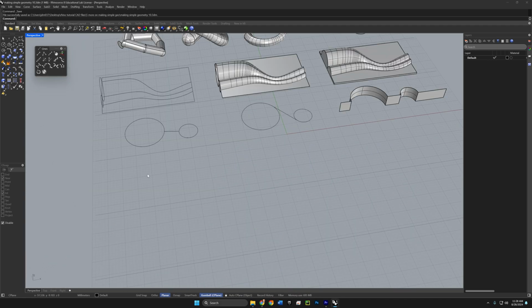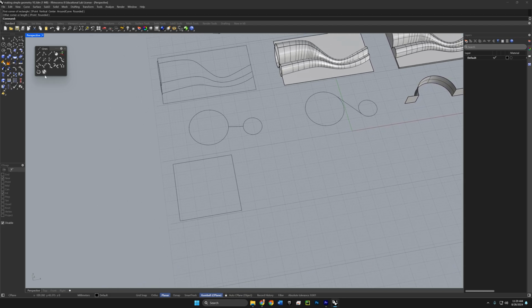In our next example, we'll look at how the curve Boolean command can help to speed up complex trims. We'll start out by making a rectangle, and we'll click here, and we'll hold shift as we drag out to turn ortho on and make this into a square. And then the next step is to create a circle that is touching at each midpoint of the square. And we can do that by clicking on the 3-point option, and that enables us to then use our mid snaps